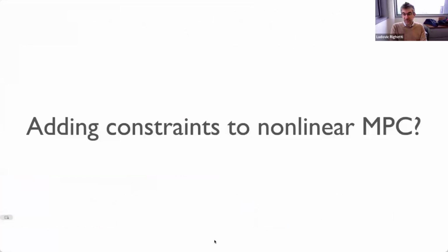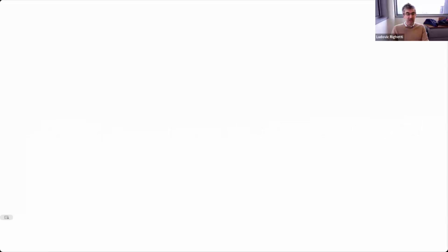One of the big problems, and that's where we'd like to show you some more technical things, is that when we do those things right now, MPC and most of the solvers are based on some sort of differential dynamic programming approach or iterative LQR. And it's not really clear how you add constraints to nonlinear MPC so you can still do things online, right? We know how to solve optimization problems with constraints, but we don't know how to do that online really well if the problem is nonlinear. And so we started to look into that kind of by chance, I would say.